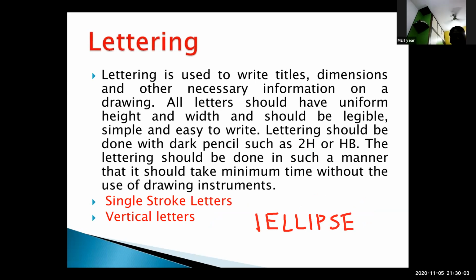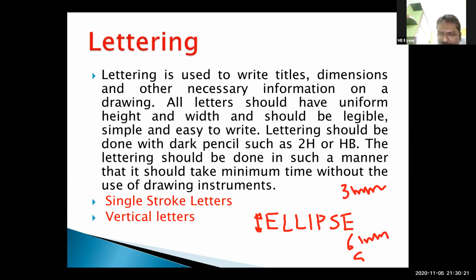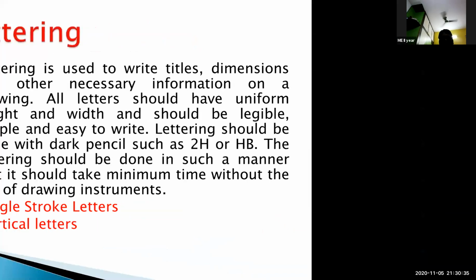The height is very important. A 3 mm height is used for notes. Suppose subtitles are there, we go for 6 mm, and if titles are there, we go for 8 mm height. The height to width ratio will be 6:5 while lettering.